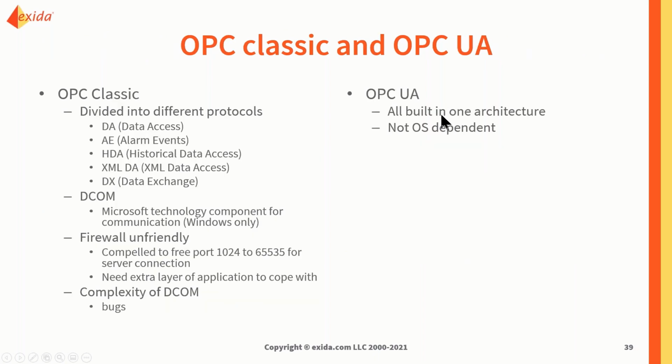Another problem that we see is about using outdated software or frameworks. For the whole presentation I stressed the use of OPC UA, the OPC Unified Architecture, rather than the OPC Classic framework. OPC Classic is an outdated OPC standard. Right now, everything is striving to transition to OPC UA.